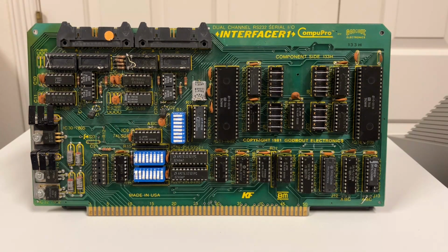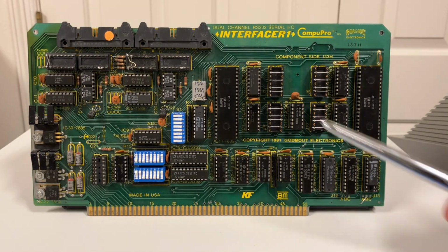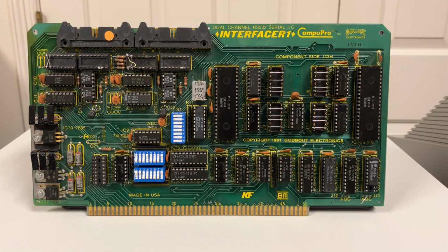Now someday if I place a minimum order or exceed a minimum order, I'll probably add one of these chips in so I have the right looking chip in there, but this satisfies the purpose and gives us our inverted data. All right, the next thing we need to do is have 8 bits, no parity, 1 stop bit. That's what these jumpers actually do. And so that's the configuration for 8N1. I've done the exact same thing over here for port A, so we'll run the console port at 8N1 when we get around to doing that.